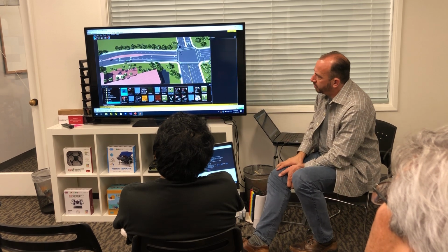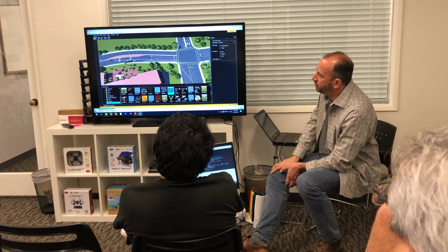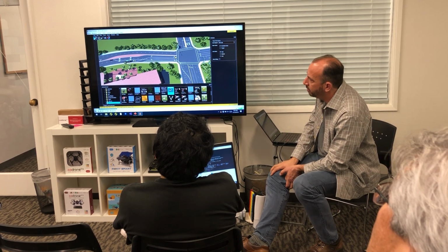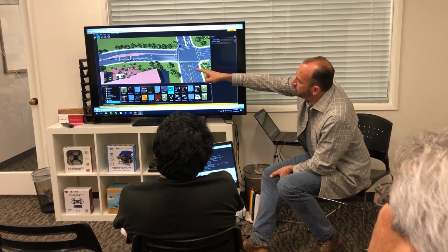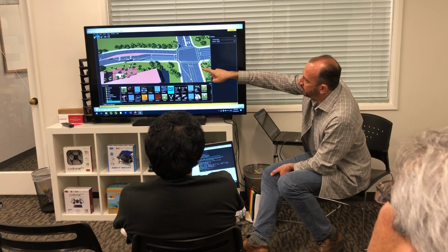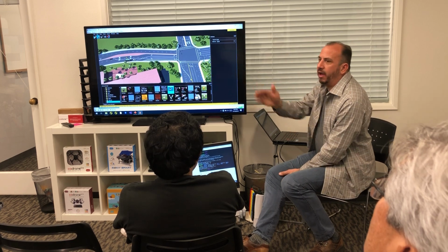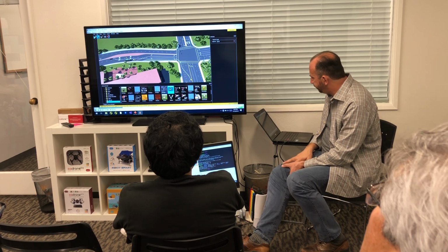We're gonna place a parked vehicle, a car that's intended to pull out in front of the test vehicle, so he's gonna follow this path. We can set up what we call a trigger. So we're placing that trigger there. When the test vehicle gets to that little lightning bolt, it's gonna trigger the white truck to drive out. So we can set that all up through the UI.